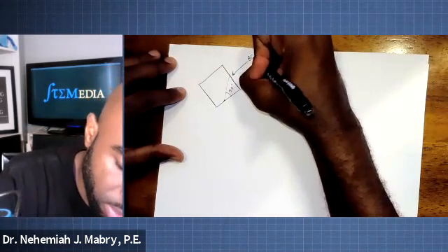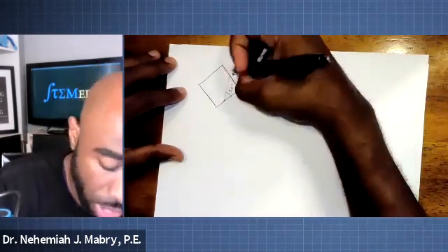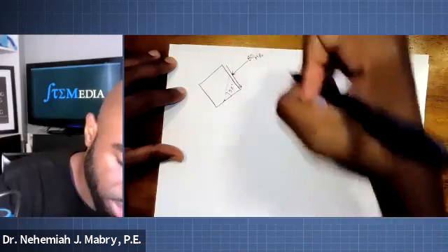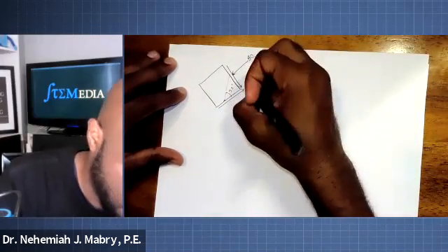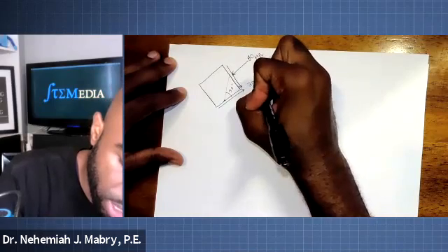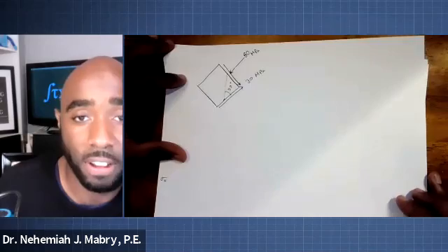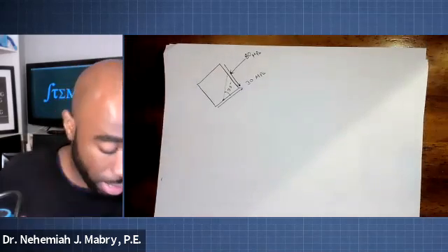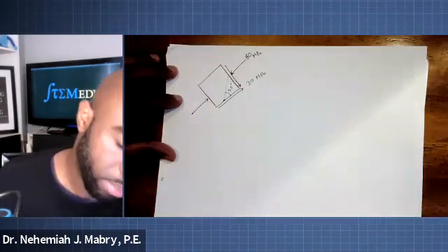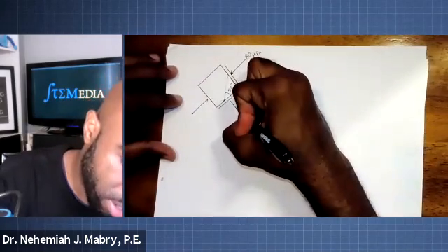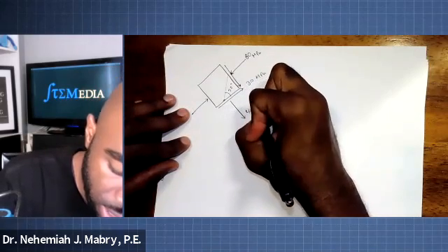It's going into the block of 80 MPa, right? And then you have another one, this shear stress here, which is counteracted by that shear stress there. This one is 30 MPa. All right, you all tracking? All right, cool. And then that's going to be another 80 MPa right there. But then you have this tension force in the y-axis of 40 MPa.